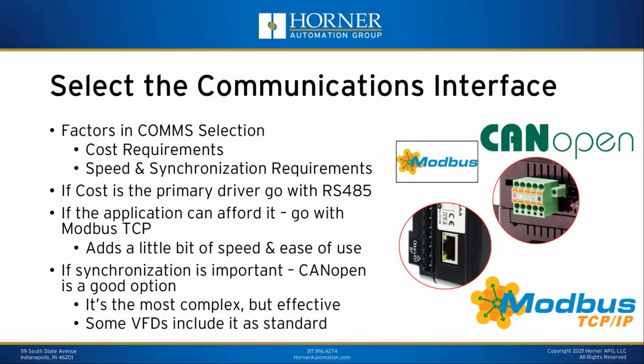So once again, there are some factors in terms of which network you choose. If cost is the primary driver, it's a low-cost application, then probably RS-485 Modbus is going to be the approach. Strictly because it's built in for free to just about every drive manufactured out there today. And while it doesn't have the absolute top of the line performance, it's highly functional.